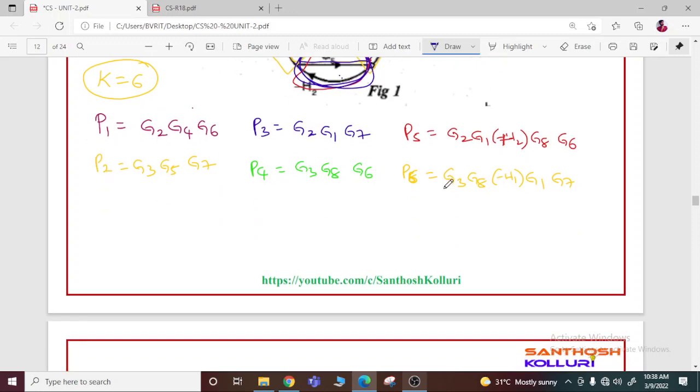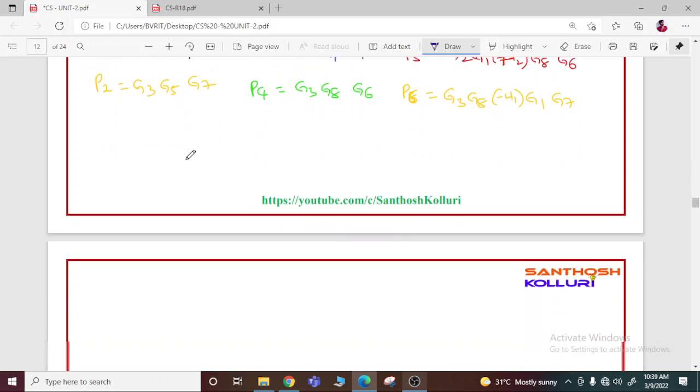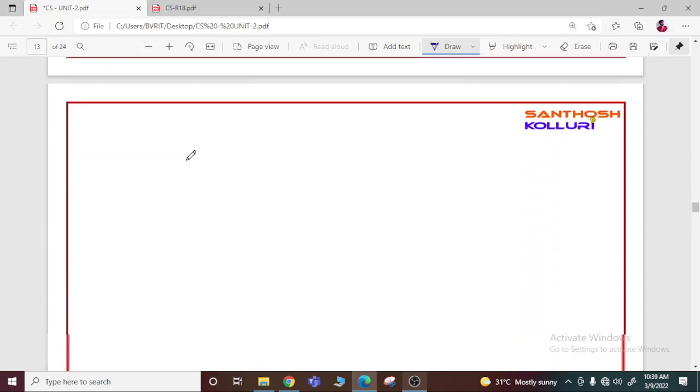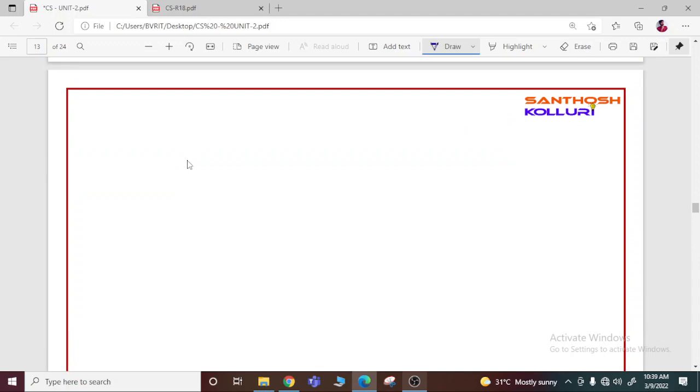So, here I have written already the forward path gains P1, P2, P3, P4, P5, P6, and I am writing the individual loop gains here from the diagram. So, I can write P11 is nothing but between node 3 and node 4, this is G4 and this is minus H1. So, P11 can be written as minus G4 into H1.